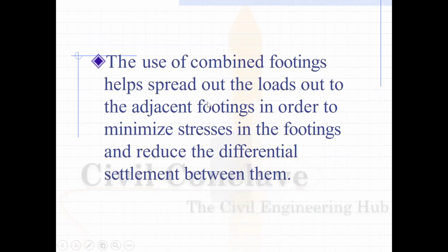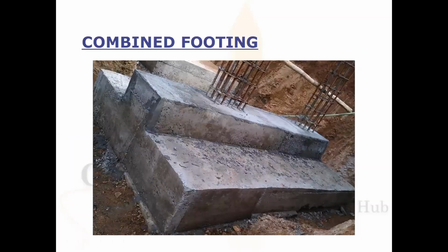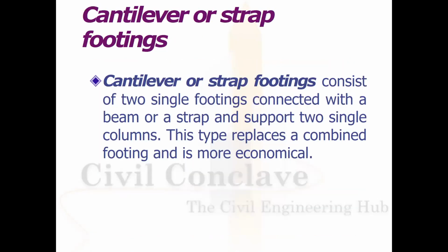The use of combined footing helps spread out the loads to the adjacent footing in order to minimize the stresses in the footing and reduce the differential settlement between them. This is the actual image of the combined footings at the site.